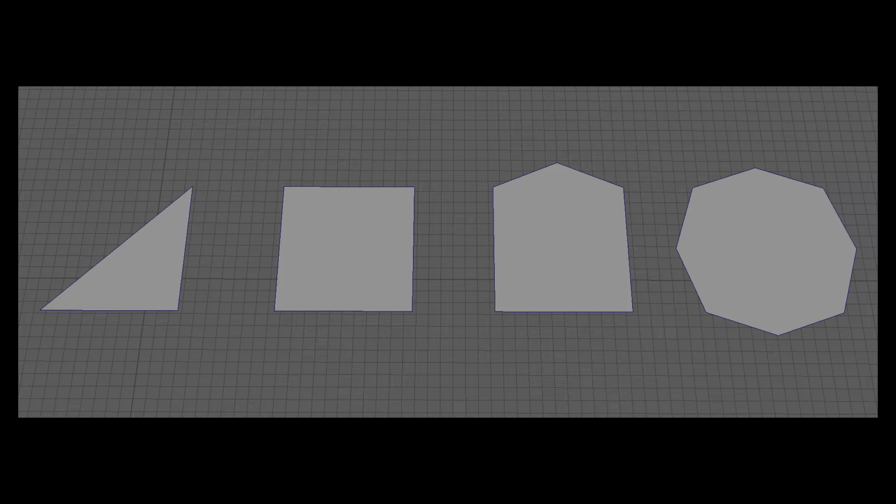And the most efficient type of geometry that you want to work with, and focus on that all your models have, is quads and triangles. And different modeling methods will require you to focus more on quads, where triangles should be minimized, or triangles and quads are usually going to be something that you're going to focus on most of the time. But then we'll talk more about the modeling methods in just a bit. But the one thing you need to know: your model should primarily consist of triangles, faces with three edges, and quads, faces with four edges. And anytime you have n-gons, that is something you want to avoid and clean up to make them into quads or triangles.